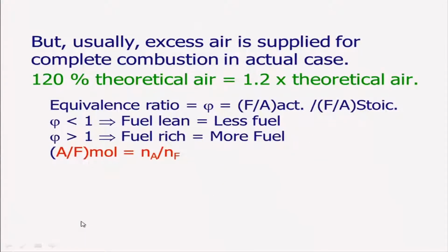And we will have to define an equivalence ratio, which will tell you whether it is a lean fuel or a rich fuel. That is defined as phi, the ratio of fuel-air actual divided by fuel-air stoichiometric. That means this is your equivalence ratio. You can define it the other way around, that is air-fuel stoichiometric divided by air-fuel actual, which some people also define. That is the same thing.